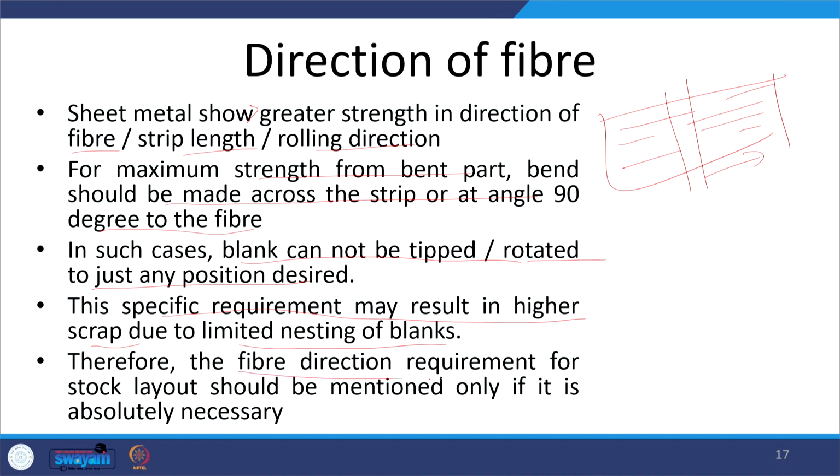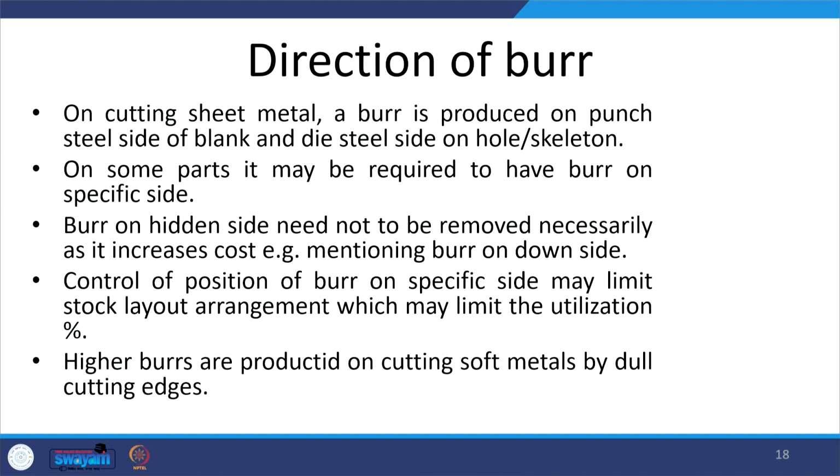Therefore, fiber direction requirement for a stock layout should be mentioned only if it is absolutely necessary, otherwise this will simply increase the material wastage, it will increase the scrap and reduce the material utilization.